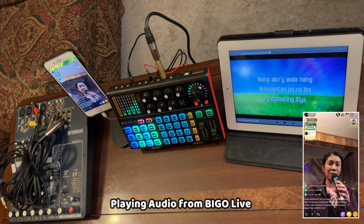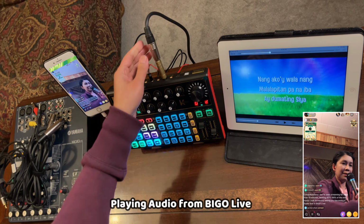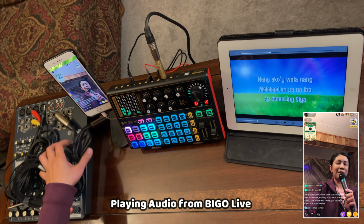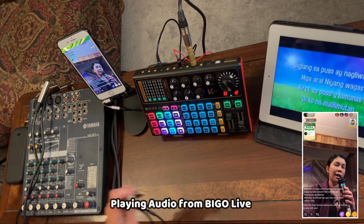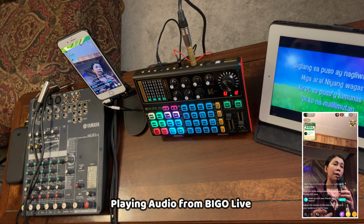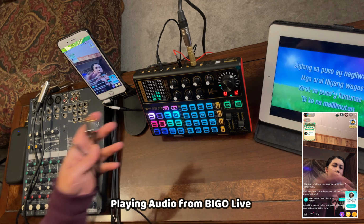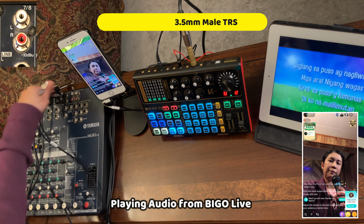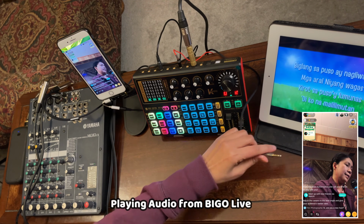Okay, there you go. So as you notice, it did work as well. So this time, I'm going to be connecting this one now to this mixer. First, we will connect this background music to the mixer. The reason why I wanted to connect the background music to the mixer is because I find it louder compared to being connected directly to this K300 live sound card. So here, we will connect the RCA to here, the one that says 7/8. And then the other end, we will connect to the headphone port of this iPad.